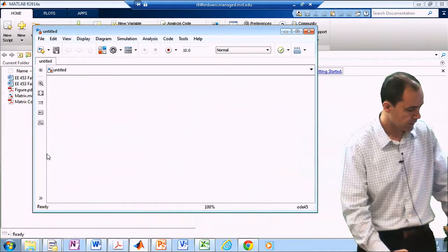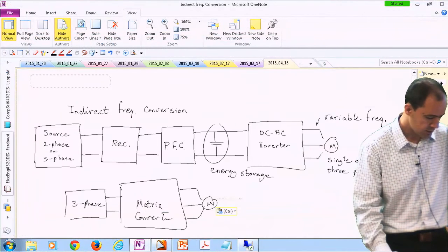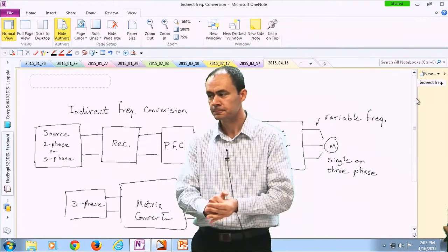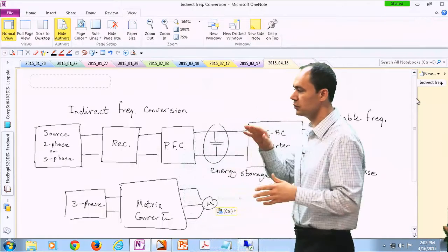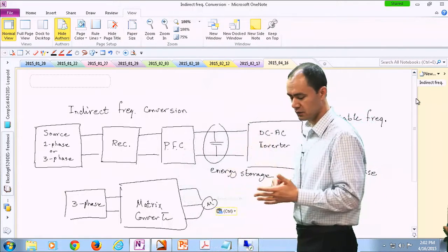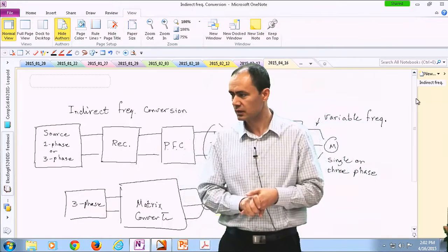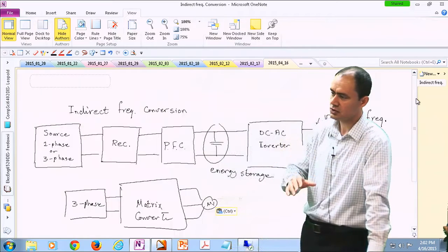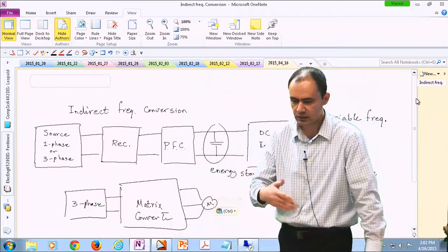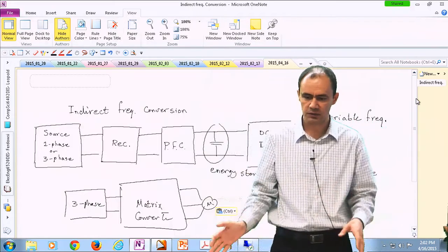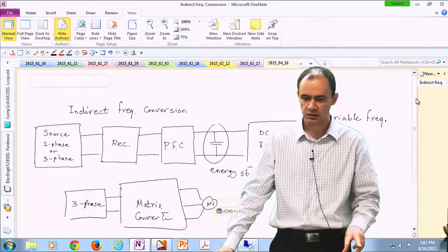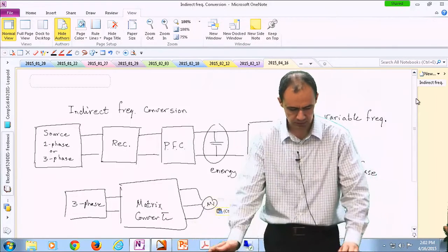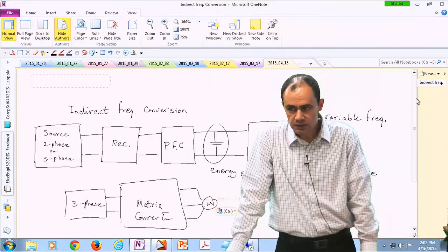All right, so that was about the homework assignment. Any questions? Yes. So what about the control part of the homework? It's open loop. It's just two sources of pulse, square-shaped signals, as your input. It's not closed loop. We are just trying to simulate the power stage, not the control stage. So D1 and D2, or the phase shift between D1 and D2, are basically two independent sources. Yeah, exactly. Other questions?